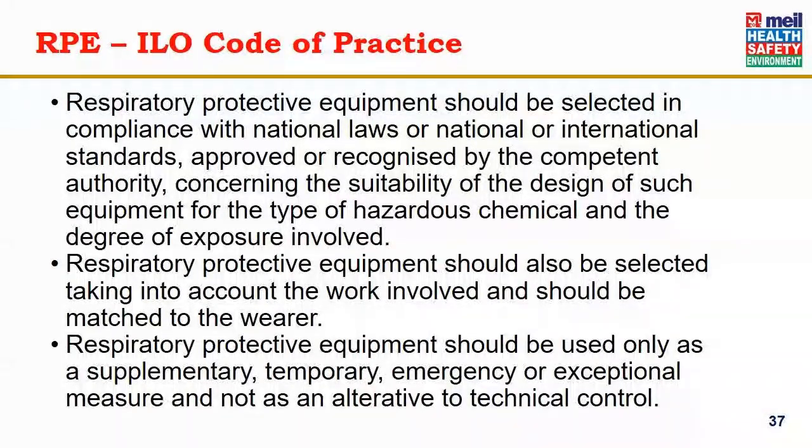Respiratory protective equipment should be used only as a supplementary, temporary, emergency or exceptional measure and not as an alternative to technical control. Once again, RPE should be used only as a last resort control measure. Before that, we should look at all the other possibilities of substitution, elimination, engineering controls, and administrative controls.